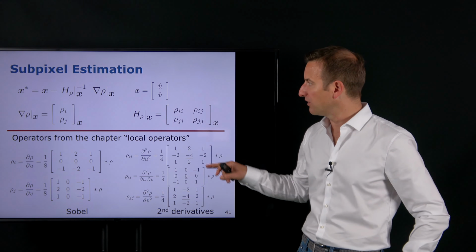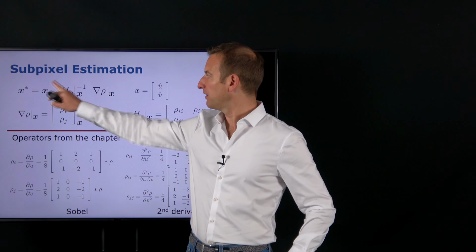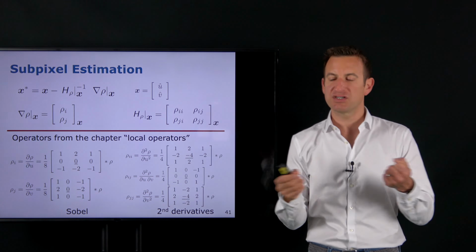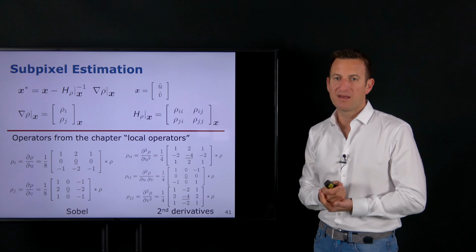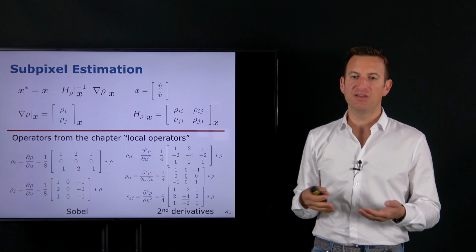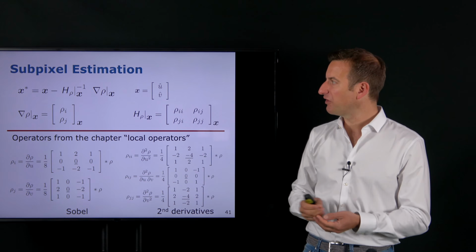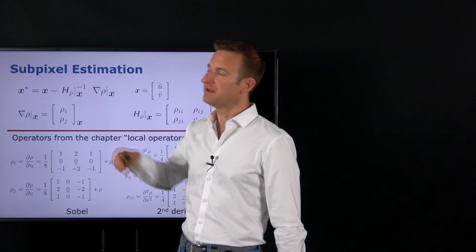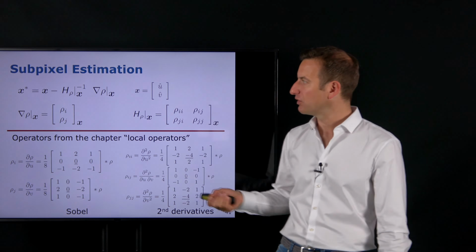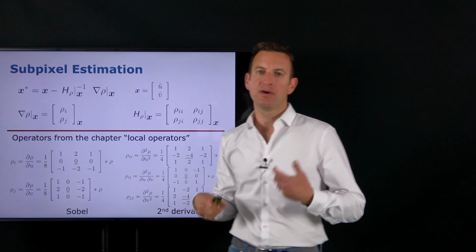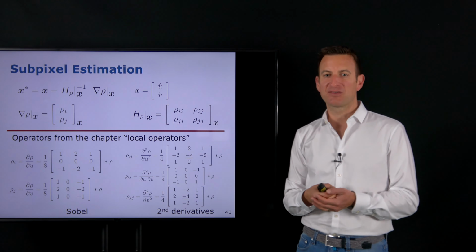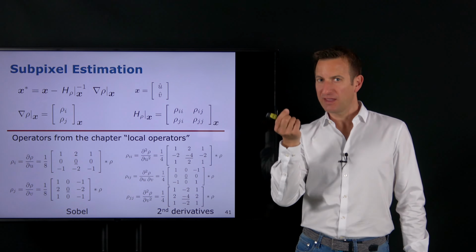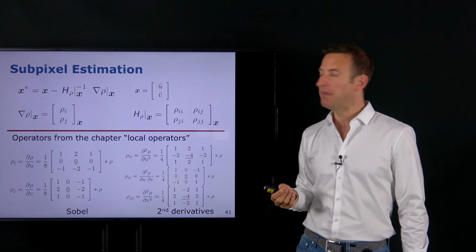Then I can start from my current estimate and take the small variation into account to estimate where the maximum value of the cross correlation is. This term gives me an update on the initial guess from my basic cross correlation, and tells me in one step where the maximum value is. So it's basically a local shift in x and y. You're going to say, okay, move a little bit in this direction, and then you're better off.